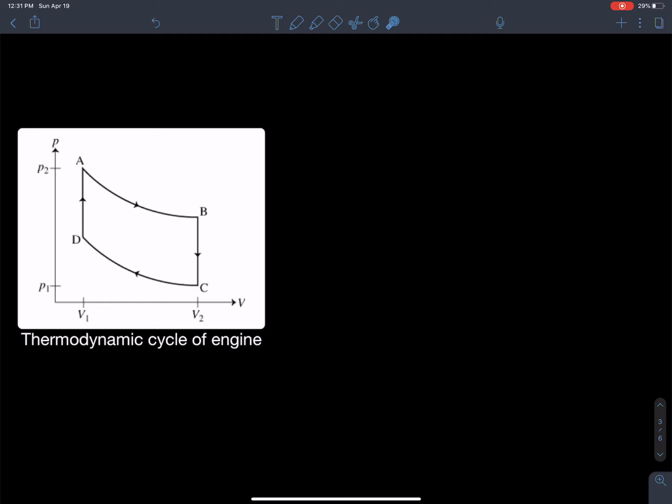And so the area inside this box corresponds to the amount of work being done in the engine. Because if you think about it, the area underneath this part of the curve is the amount of work that the environment is putting back on the system to reset it. That's by cooling it and squeezing the bulkhead back down again. So all that would be lost energy. And then the front part, all the total area under here would have been the work done in the combustion, but then we have to subtract that part to reset the piston back to its original form.